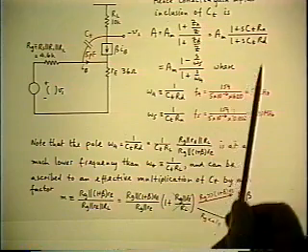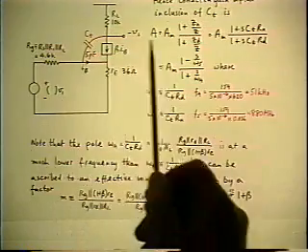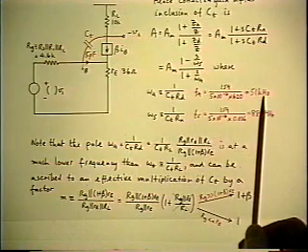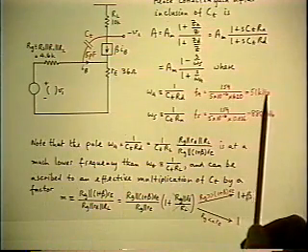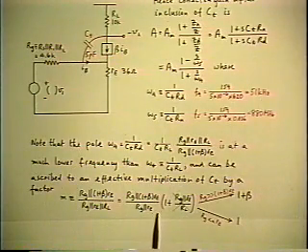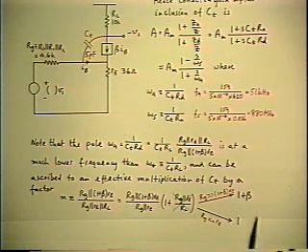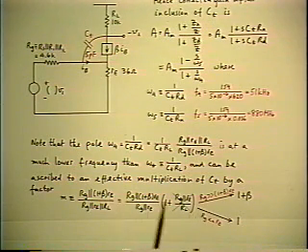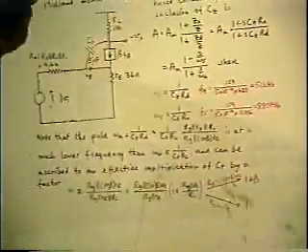Now the multiplier is inside the RD, so it determines the pole of your amplifier gain, which basically determines its bandwidth. So if you're trying to make a wide bandwidth amplifier, you want to keep the multiplier as low as possible. This tells you you better keep the RG as low as possible also, which you probably know already as well. But this is a very compact summary of all that. In fact, it's even useful to plot a little sketch of the value of the multiplier as a function of RG.